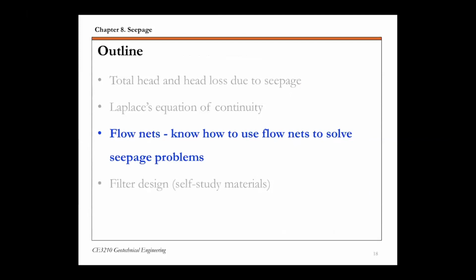So this leads us to the next topic of this chapter, flow nets. For this course, what you're required to know is to use flow nets to solve seepage problems. Basically, if you're given a flow net, can you use it to calculate seepage quantities, head at any location, pore pressure or water pressure at any location, and the factor of safety against piping or heaving?